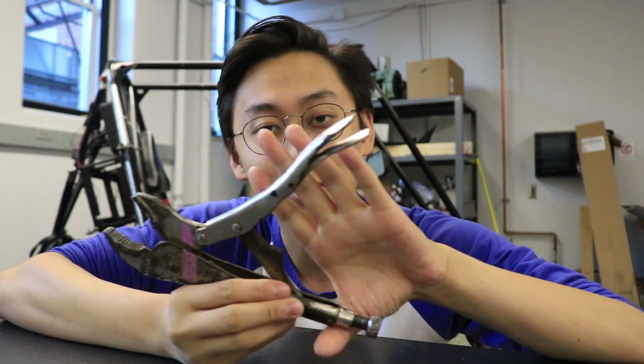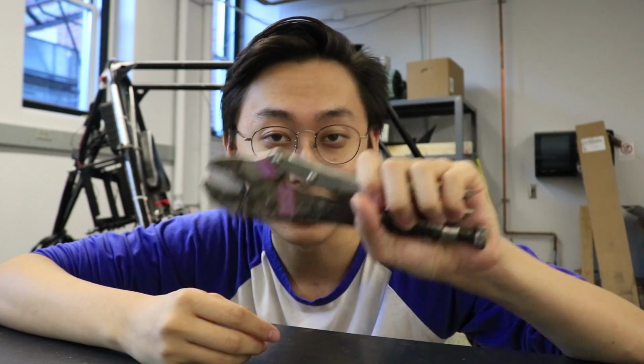Real nice and easy. Why are we using a 4-bar? Because when we hit the 4-bar toggle point, there's so much force onto the 4th bar that it will lock our motor into the steering shaft, kind of like how these work. This is a vice grip in case you don't know, but you should.